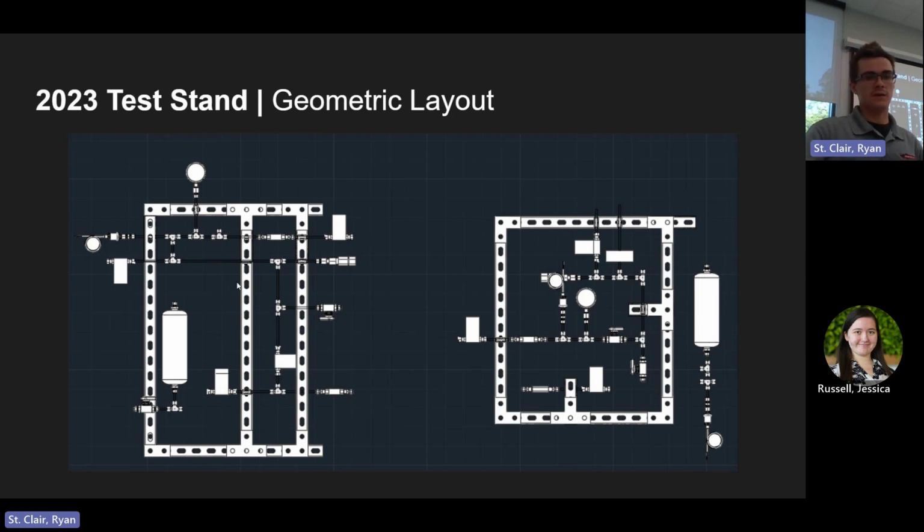So again, we have this ethanol feed system here, to follow the path of pressurants, just to relate the 2 together. You have pressurant going through this control valve, across this check valve, and then through this flex line that's not pictured in here because it would be hard to represent a flex line in something like AutoCAD. It enters into the system and is able to blow down that ethanol through this control valve here and out here.